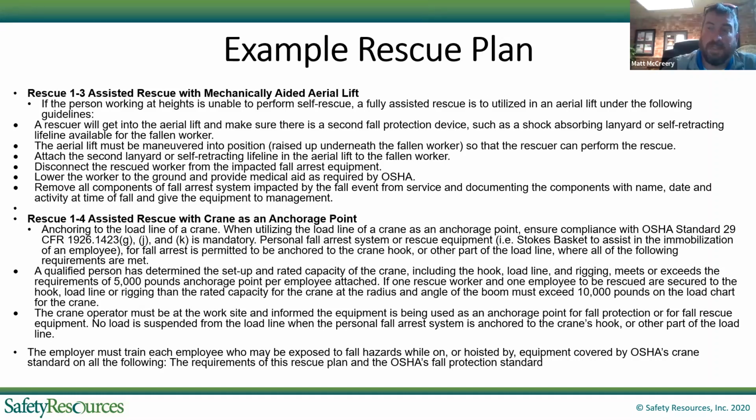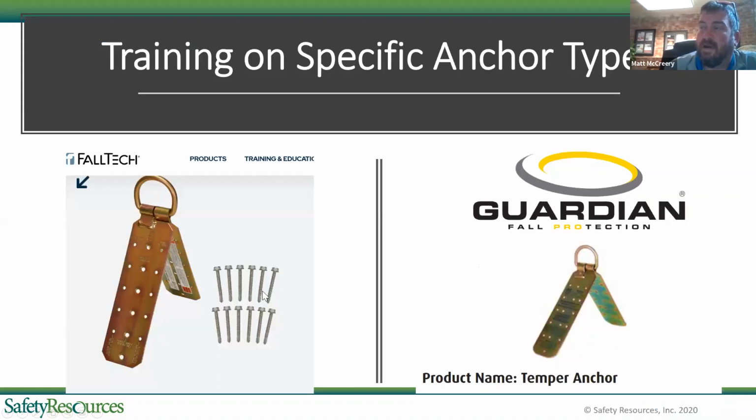However, a best practice that we talked about when low slope roofing, if you're completing a site specific safety plan and this is mentioned within it, this needs to be actually discussed and the crew needs to understand, hey, listen, if I were to fall and I'm dangling 60 feet in the air, how am I going to get back up? Okay, we're going to use the crane, and this is how we're going to do it. It doesn't have to be an 8-hour training anyways. It can still be a 20-minute, 10-minute thing, as long as they understand how it works.